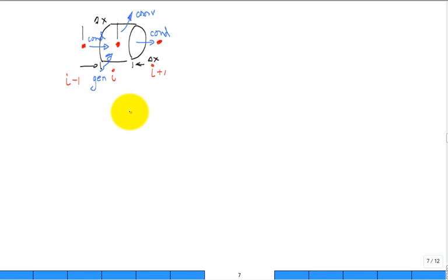And when I write the energy equation, what I recommend is when you write these, you write them for everything going into a colder node, and everything around it mathematically is warmer. Just think about that for a minute. Just turn it around. Instead of having some of the conduction out, just put all the conduction in. Let me try and fix that. And the convection, instead of making it out, make it in. So then I have just the sum of all ins equal to 0. Everything's in. How do I write it mathematically?